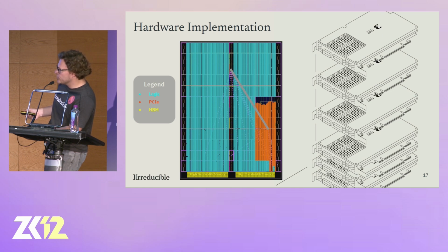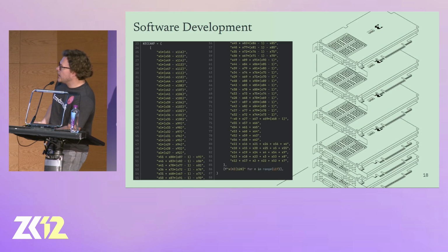The yellow portion at the bottom is on-chip memory. This is a pretty big 16 gigabytes of memory inside the FPGA, which we use for data and instruction storing. The orange color is the PCI controller that talks with the motherboard and the host, and then everything else is the logic, which carries 48 of these cores in a multi-core CPU. So we implemented this internally, tested it, and I will also share a little bit about the software implementation.